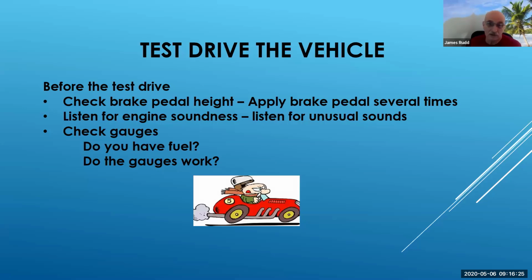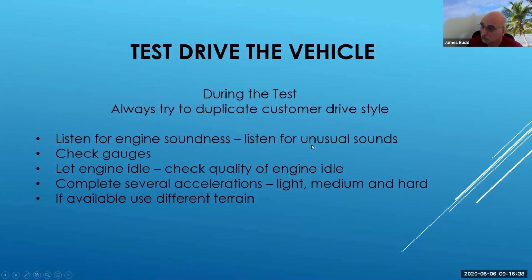Do all the gauges work too? You want to see if they're all operating. If I have an oil light on and the gauge is all the way down and I hear a lot of clattering going on, that car isn't moving. I've already checked the oil by that time too.